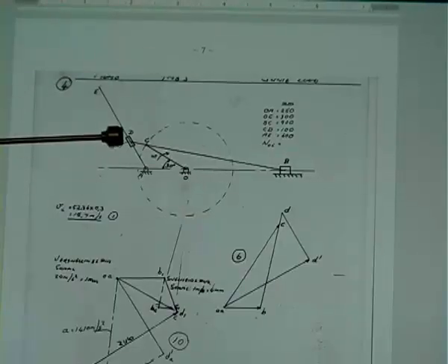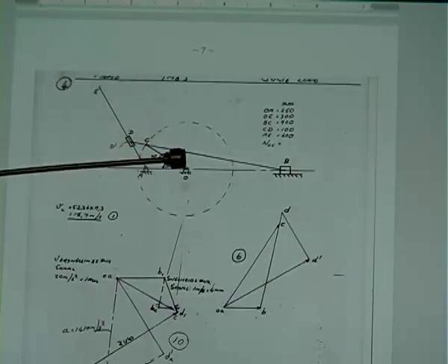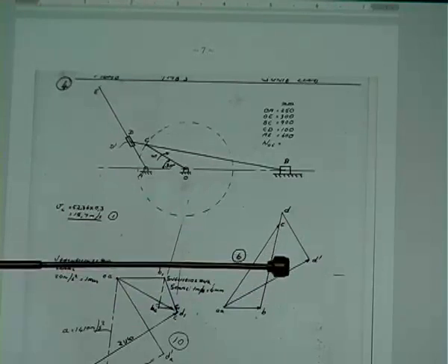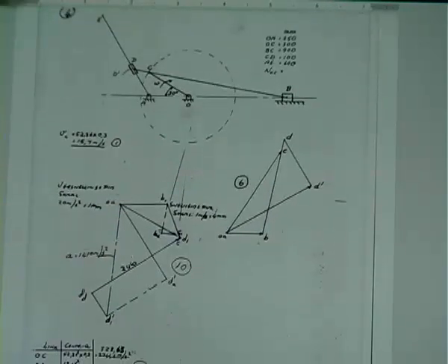So your mechanism, first what you're going to do is draw a line diagram, also called the space diagram, of your mechanism at a specific position. From your space diagram, you're going to construct your velocity diagram. You get information from your velocity diagram to construct your acceleration diagram. The reason for constructing your velocity and also the acceleration diagram is to do some calculations and see the force or the torque acting on that specific link.